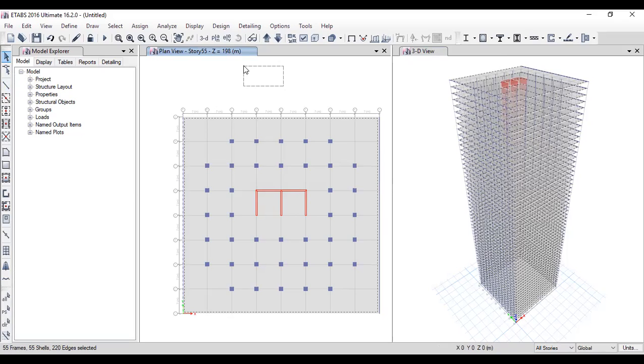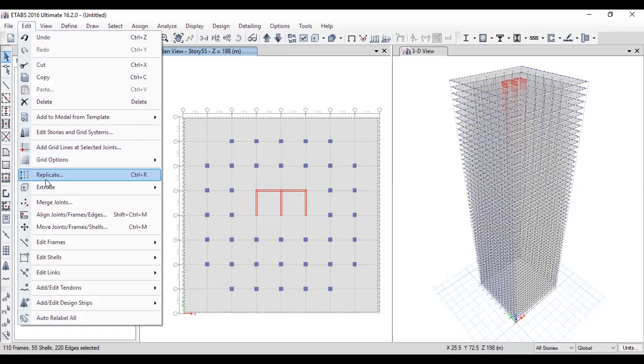If you go in this way, whatever touches this box will be selected, and if you go this way, you will only select the full elements within this box, right? It's like AutoCAD. See here, this beam is not getting selected, but if you go from here to here, this beam will be selected. So now the floor and two beams are selected.